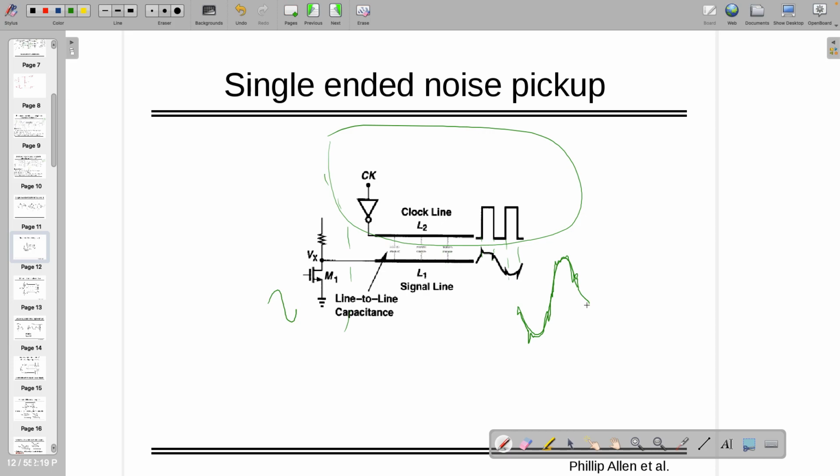So actually they are connected through a parasitic. You can see here there is a frequency signal, here also a frequency signal, so both can be connected through some sort of parasitic capacitance, and it depends on how close you are keeping that. Of course you can get rid of it through the technique which we are using, right? But sometimes people are using the normal wire on a breadboard, right? So on the breadboard itself, it can pick up the frequency signal which is nearby, so we have to get rid of it, right? So what could be the suggestion to get rid of it?